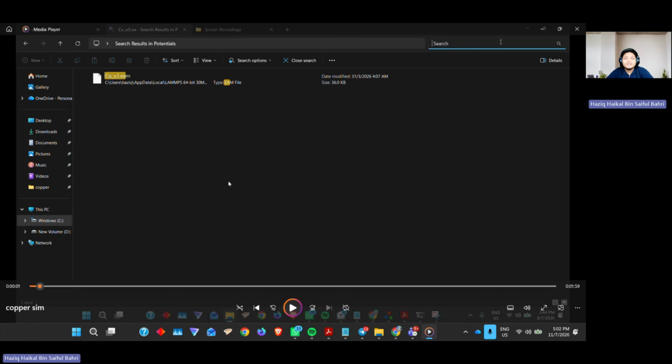Thank you, Azri. My name is Haziq Aikal, and today I'm going to show you how we both simulate copper and argon using LAMMPS. So first thing first, I'm going to show you how we simulate copper. For copper, we are going to use EAM potential so that it can show a more realistic crystal behavior. So what is EAM? EAM stands for Embedded Atom Method.